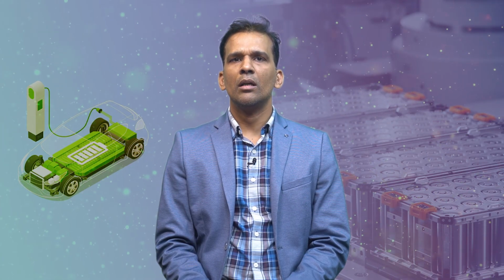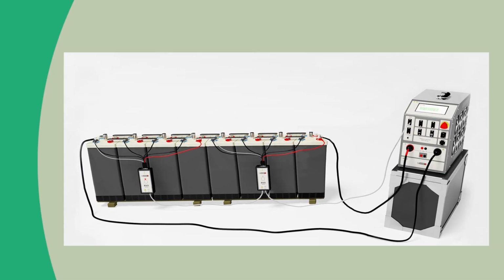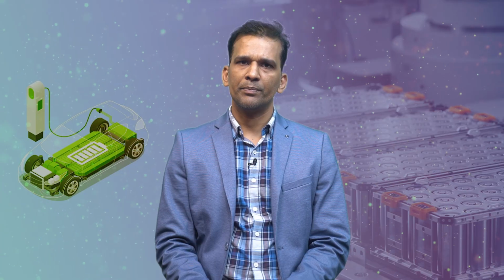Also, this voltage is critical for what we call cell balancing. Once it is in the normal case, most of the time cell battery voltage measurement can be done using the different potential divider method. However, we can also use different types of Hall sensor, but it is a costlier choice. So that is why the potential divider method is mostly used to measure the battery voltage.